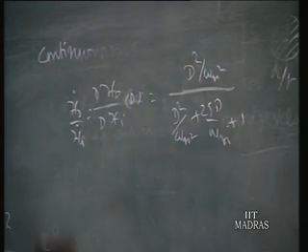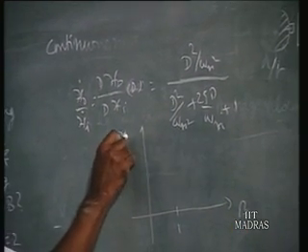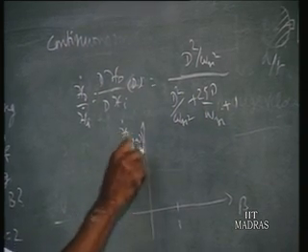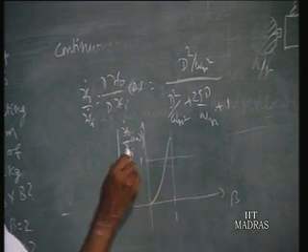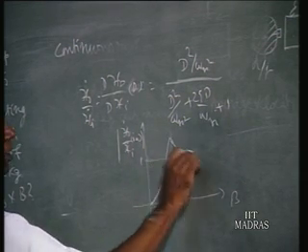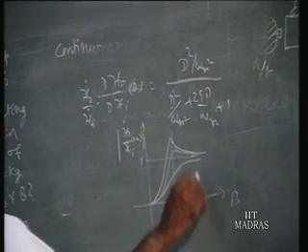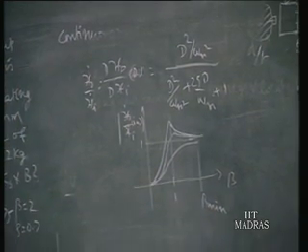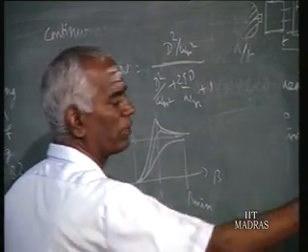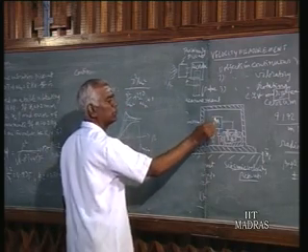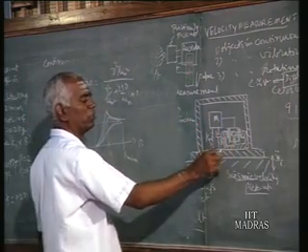Now we know the curve for this right hand side, beta, this is 1, this is magnitude of xo dot by xi dot at i omega. Now we know it starts somewhat like this. So suppose this is the 1, it comes like this. Same curve we have seen for absolute displacement measurement, that means the measurement range starts from beta minimum, same considerations. So only when beta is more than beta minimum can it measure the input velocity in terms of output velocity. So we are measuring output velocity, that is the relative velocity of the mass with reference to the frame of the instrument, measured as xo dot.